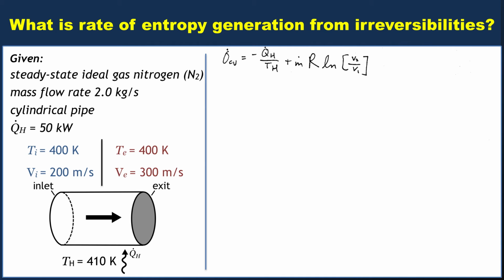Well, we can get that through the mass flow rate. So obviously in a steady flow, m dot i has to be m dot e. There's only one inlet and one exit. And if you remember, you can write m dot as either the density times the area times the velocity, or the area times the velocity divided by the specific volume. That latter one will be more interesting for us. So A times the velocity over the specific volume is the same at the inlet and the exit. And just to be absolutely clear, you can substitute in that the exit specific volume is little v2 and that the inlet is little v1, right? You can think of this either as inlet and exit or as a process happening to one parcel of gas. It's equivalent. So our goal is to solve for little v2 over little v1.